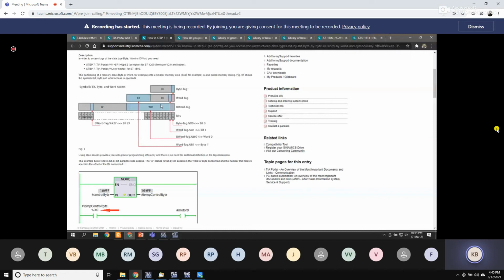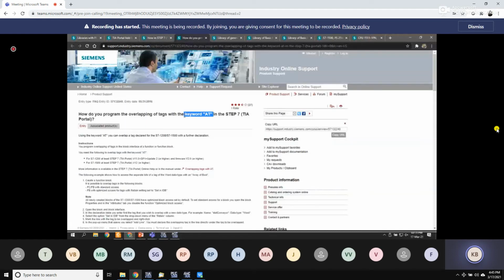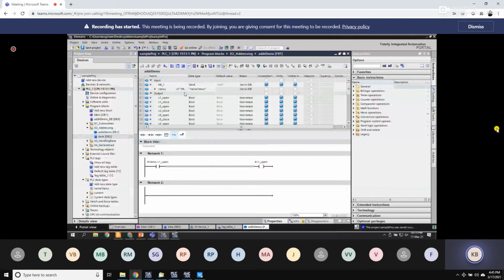a tag. So for that, we use the AT construct, the AT keyword. So using the AT keyword, we did that. Now, using the AT keyword, we saw that we had to use the struct to make full use of it. Using struct was totally okay, but if you want to reuse that same structure somewhere else, just like how an input module can itself be used in these cases, instead of keeping some struct, I made it as a user defined data type or UDT.